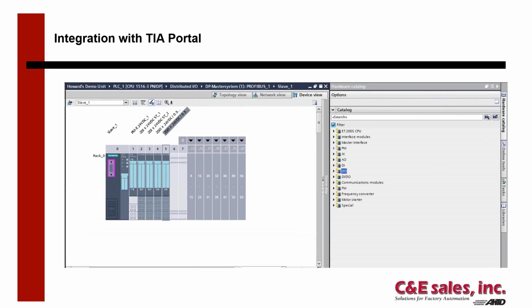That was my task. It turns out that every Profibus device out there has to provide at least 6 bytes of diagnostic information. Anything after that, the manufacturer could provide more diagnostics or not, but everybody had to provide at least 6 bytes. And one of the bits in those 6 bytes says, hey, the master isn't talking to this slave anymore. You've got a problem.